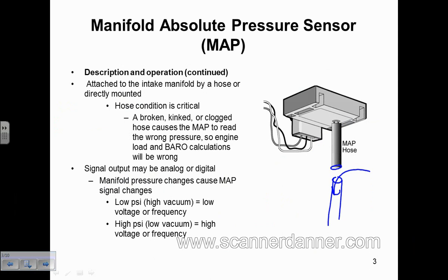But this is, let's say this is the primary one, a vacuum leak on a MAP sensor. This engine is going to run extremely rich. Actually, let me take that back. This engine runs extremely rich at idle and low speeds, but runs completely normal at wide open throttle. If you think about the MAP sensor and its operation, that would make sense. What do we have as far as vacuum at wide open throttle to this MAP sensor? No vacuum. We've got full atmospheric air going to this MAP sensor at wide open throttle, right? So that's what it normally would read.